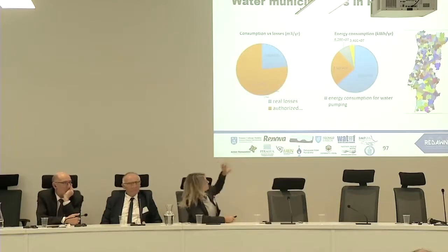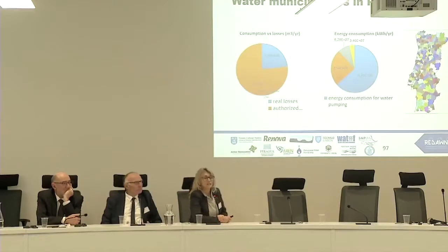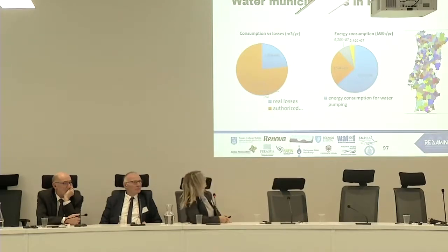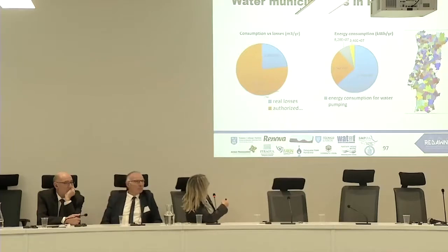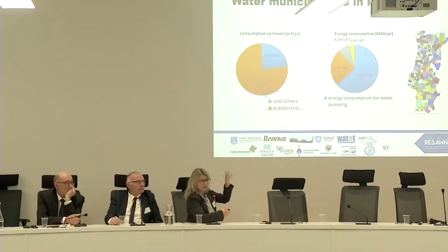Well, here, this is a summary based on the data given by my colleague, Roy. But it is interesting to see the consumption versus losses. Here we can see the real losses in the authorized consumption like this. On average, we have more or less 25%, in a gross analysis through the whole of Portugal's water municipalities.